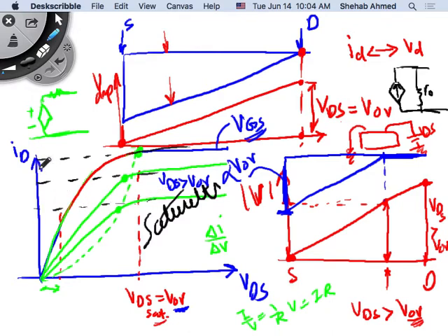So this is current that is fixed, right? It's current that is fixed. That depends on what? This is one value of current, it depends on this gate voltage. This is one value of current, depending on another gate voltage. Does it depend on anything besides the overdrive or the gate voltage? No. So we have a voltage-controlled current source.